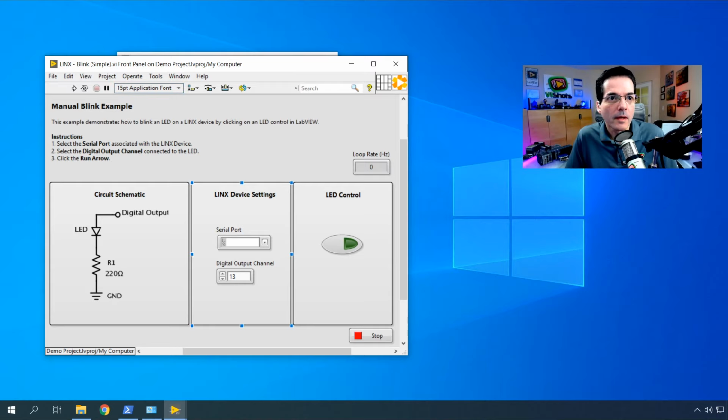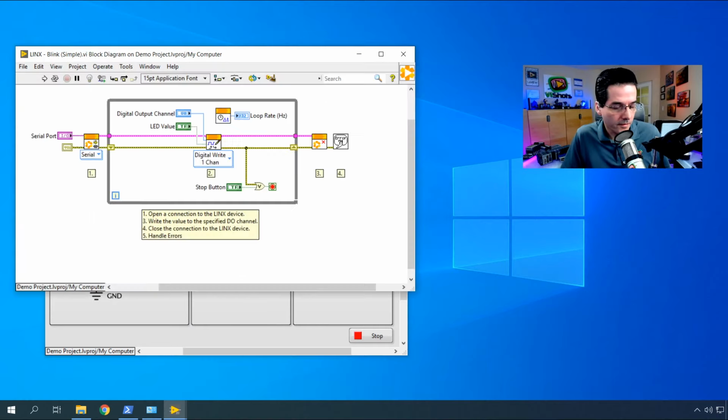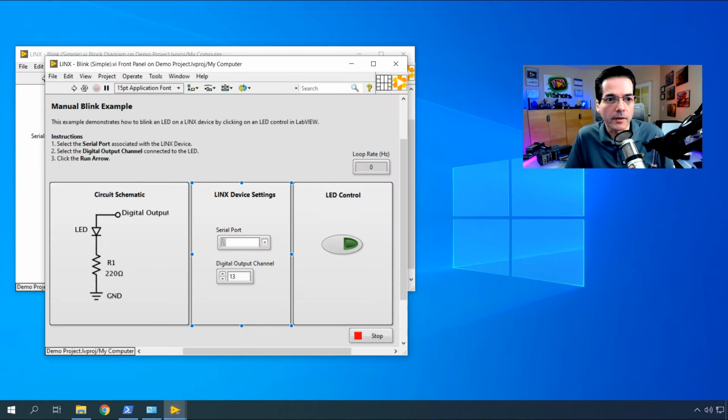And this VI is a very simple VI, and it opens a connection, outputs a digital line state, and then closes the connection. So this is a very simple example of how you can communicate with an Arduino. Now this open connection here, as you'll see, it has serial, it has other options. Take note of this local I/O. That's an interesting one. We'll look at it later. But this is how you do a basic setup for Arduino. So I have mine connected to COM3, so I'll connect that.